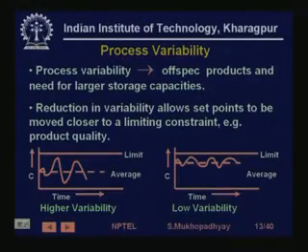If the bar has cooled down a little bit because it was waiting to be rolled for some time, so its temperature has fallen, then it will become considerably harder to roll, and therefore the dimension reduction may not be appropriate, right. So, such things can give a lot of process variability.